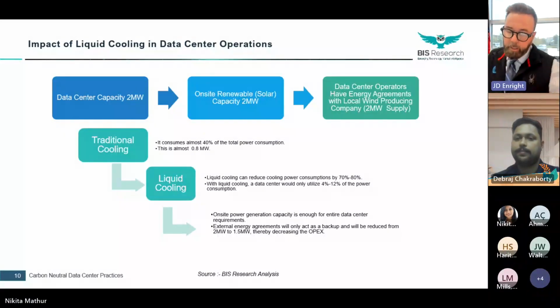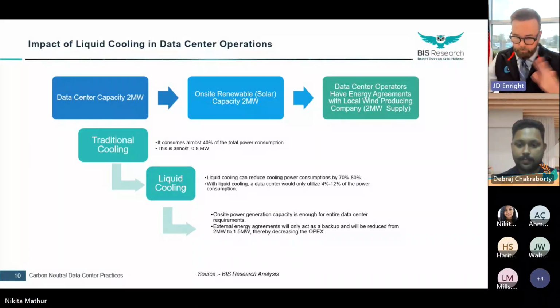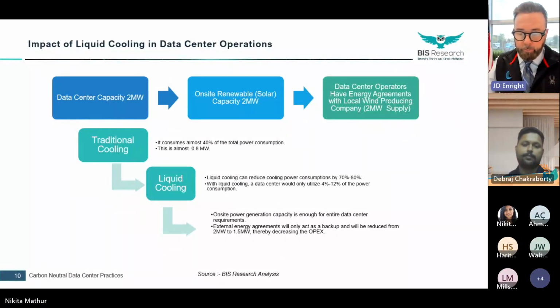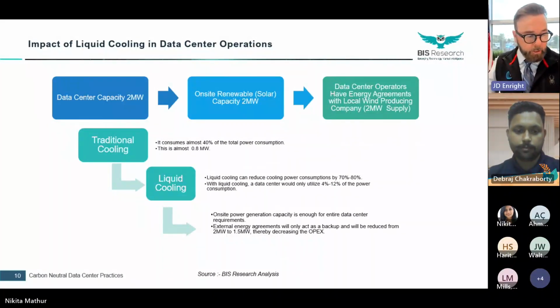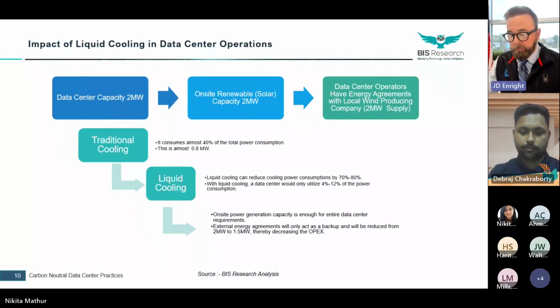Yes, and I'd like to back up a bit here just for a minute. Whether it's single phase immersion or two-phase immersion, there is a water requirement, and that requirement is for the final heat rejection. I just want people to clearly understand that. It doesn't eliminate water 100%, unless you're doing a dry cooler and you're in the smaller units. And then yes, that is an absolutely accurate comment.